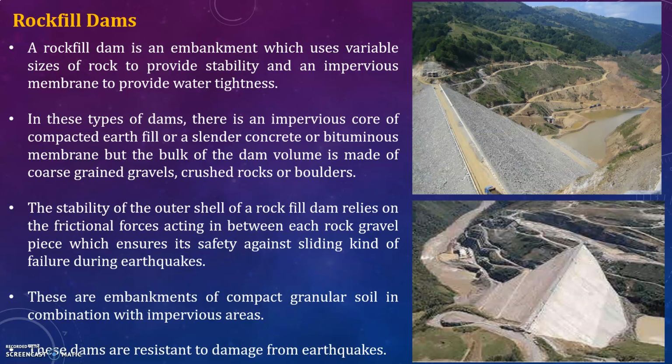Let us discuss some of the disadvantages of earth and rockfill dams. They are more vulnerable to damage by floods and fail suddenly without sufficient warning. They cannot be used as overflow dams. Separate spillways are to be provided at some site away from the dam to pass the surplus discharge. They are not suitable at the locations where heavy downpour is more common. They require heavy maintenance cost and constant supervision. So this is about Rockfill Dam.